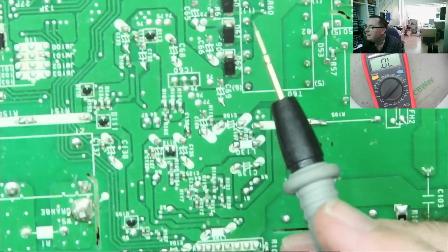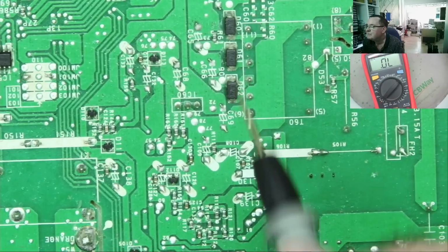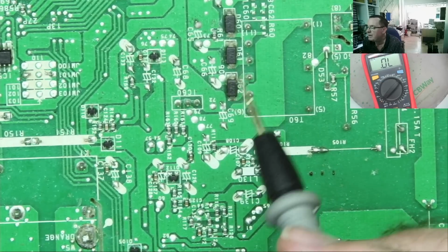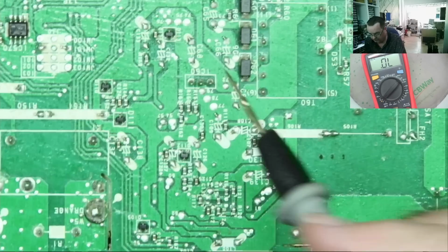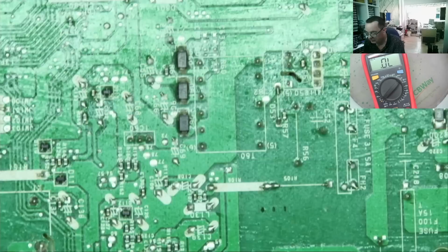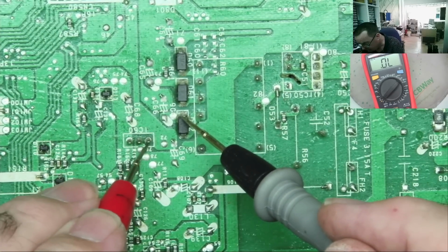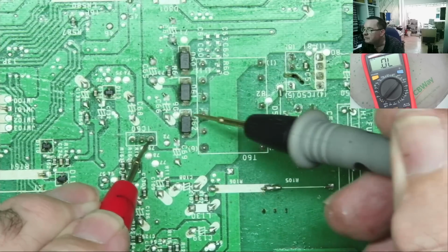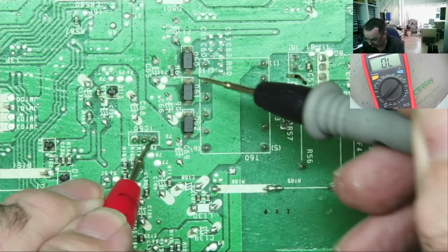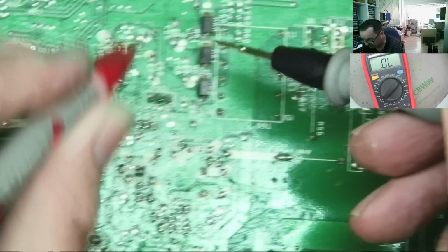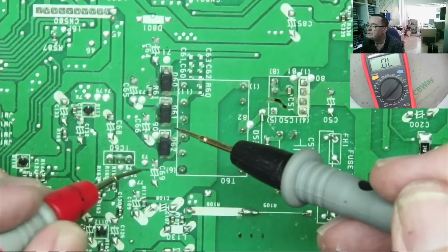I see 3 diodes directly by here, so I think we can say there are 3. We're going to have a supply feeding into this, the regulator. This is the input pin. Expect that to come from one of these diodes. Yeah, that one. So that is feeding that 5 volts, and then there'll be a plus and minus supply here, I would imagine.